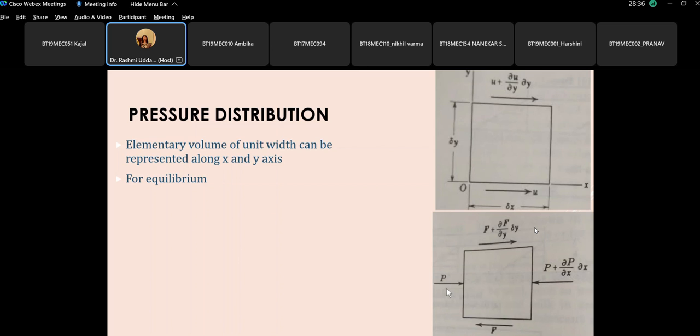And if we talk about the pressure on the oil, which is coming into picture because of the load it is carrying, the oil is forming a converging film and it is also carrying the weight of the journal. So there is a component of pressure also, and this pressure is also varying because it's a converging film.